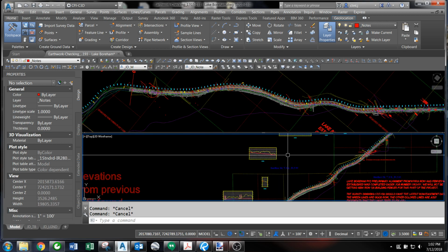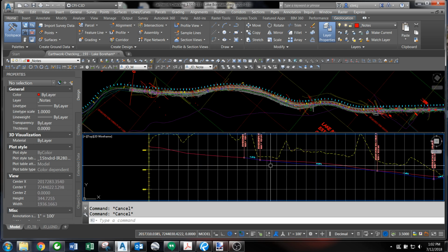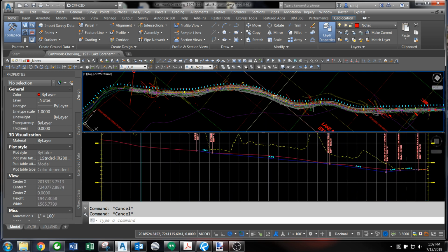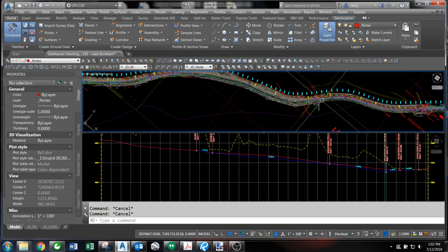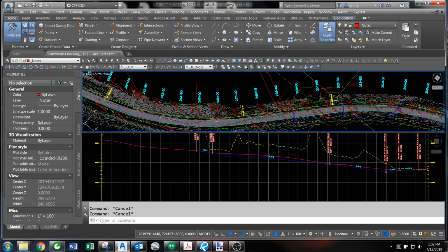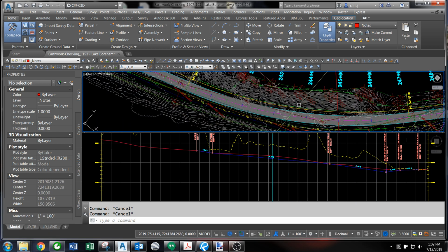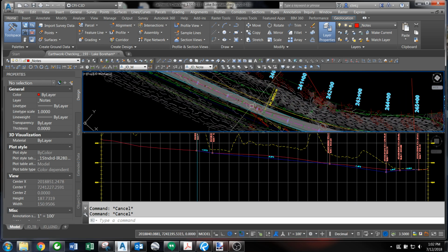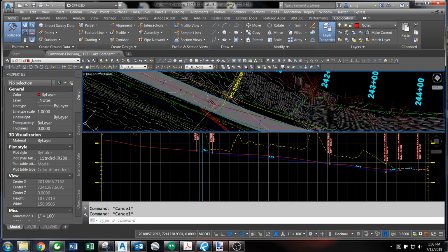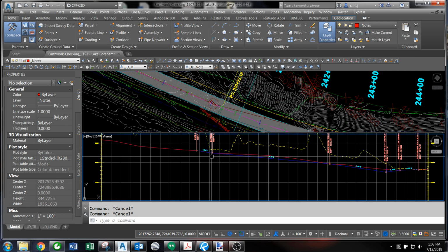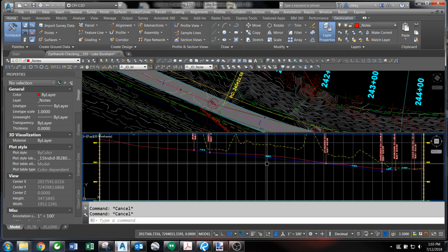You come to this next one here. This next one up, this will probably be the last one I show you. So here we come, and now we're almost getting to the driveway and the dairy here. So here's the dairy and here's the driveway, and we got a culvert and an inlet basin right here. You can kind of see my profile there. Here comes the ditch as built by the typical section, and then right in here I start diverging because I wanted to steepen that ditch up a little bit to make sure we got good flow coming around that corner.